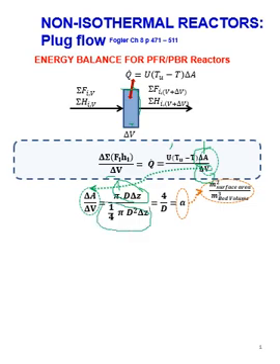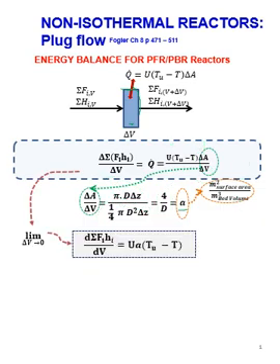So here I end up with a parameter a, which is equal to 4 over the diameter of my tube. That gives me the surface area available for heat transfer per reactor volume. So when I now include that in my energy balance and I take the limit where delta V goes to 0, that is still a function of my tube diameter, and I can say that the change in enthalpy per volume in my reactor must be equal to the amount of heat transfer, where I have an area per volume parameter to express that heat transfer.